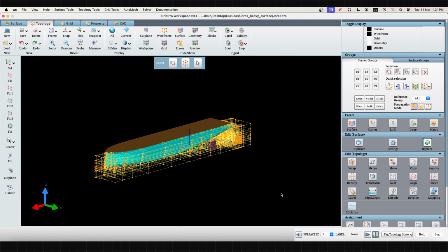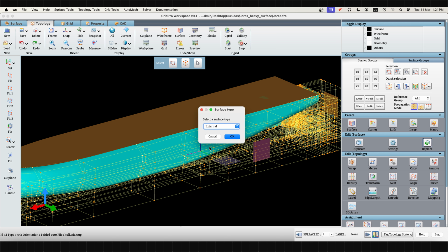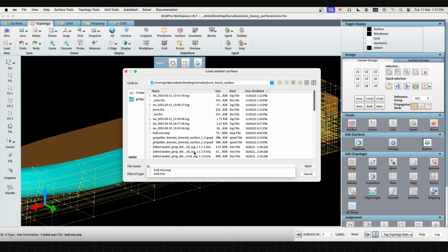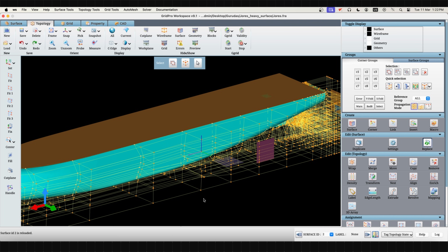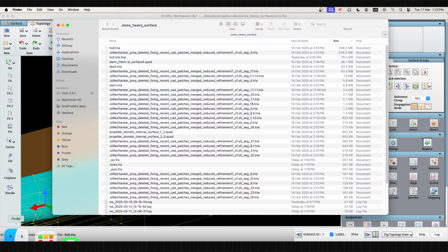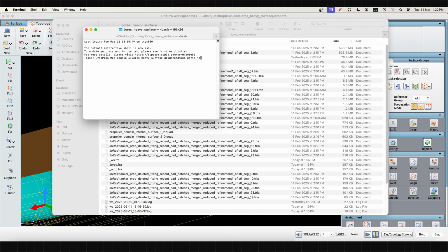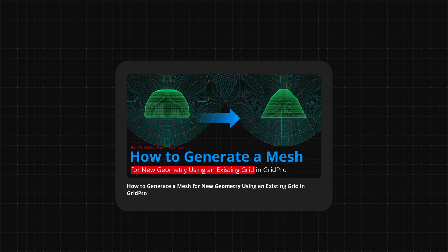At the end, when you have created the complete topology and are ready to create the final grid, you can replace the originally triangulated surface in that final topology step and run the grid smoother. Learn more on replacing the surface file.